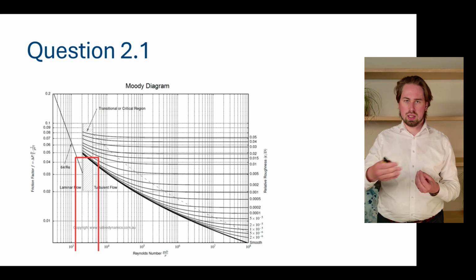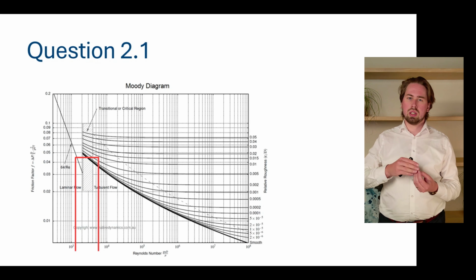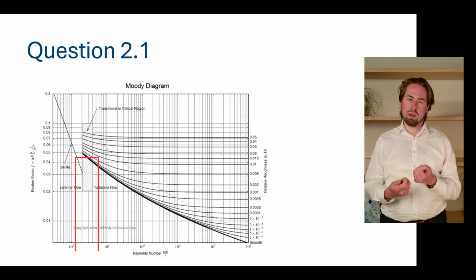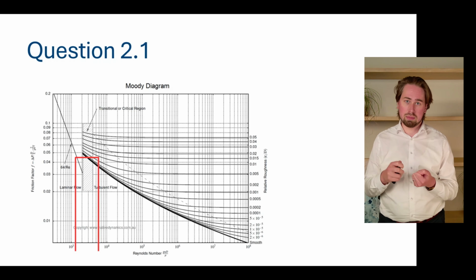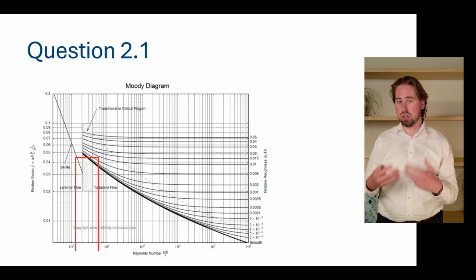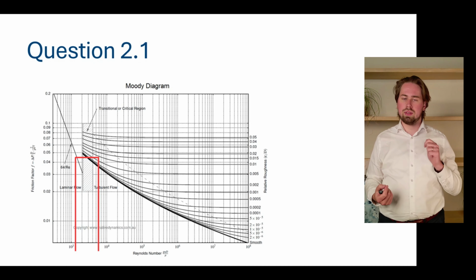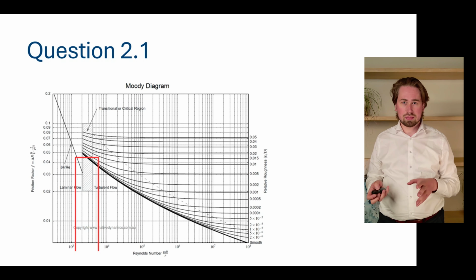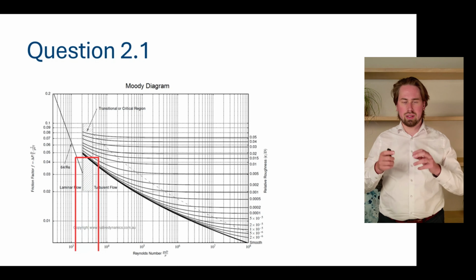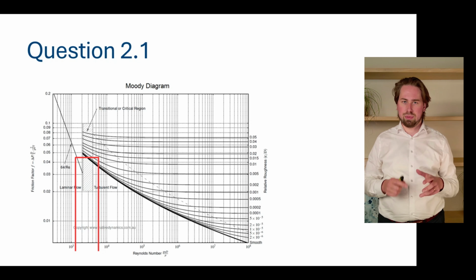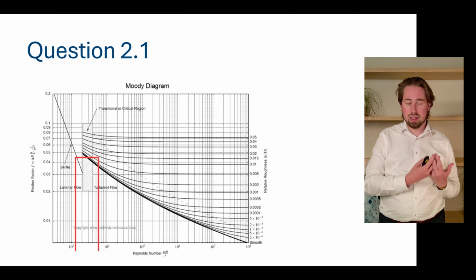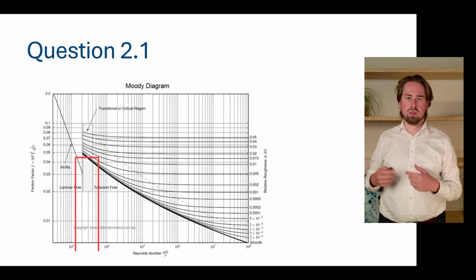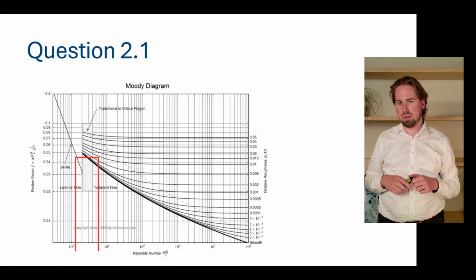But when our temperature increases during injection, we actually have a higher Reynolds number, and we're now in a turbulence regime. This means we have a different friction factor, and it can in fact be that this friction factor during turbulence is lower than when we're working with a laminar flow rate. Because in both cases our flow rate is the same, it's exactly this difference in friction factor that determines that we can indeed have a pressure drop in a laminar flow that's higher than during injection when we're turbulent.